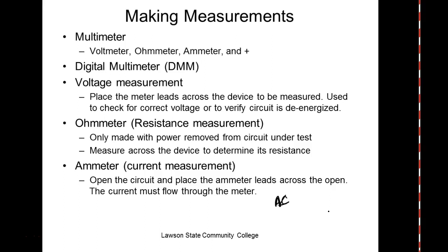So we add another circuit that we call an overload, which basically looks for if the motor pulls too much current over a certain amount of time. And if it does that, it'll trip out the control circuit. We have heater overloads. Now, the advantage of heater overloads is that they work off heat and they're very cheap.